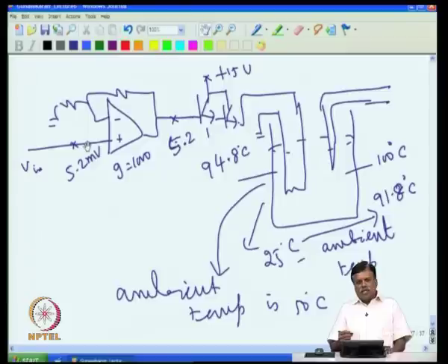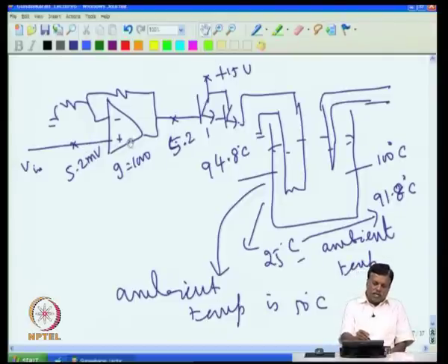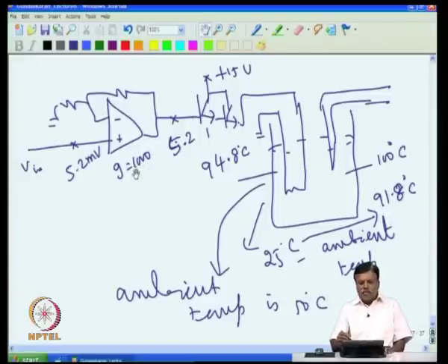If the temperature has to be constant throughout the day, then the only choice is to increase the gain. Do not keep low gain, you go for high gain, but high gain will make the temperature go up and down. If you keep it at low gain, then from morning to evening, if you watch the temperature of this, it will be changing slowly.